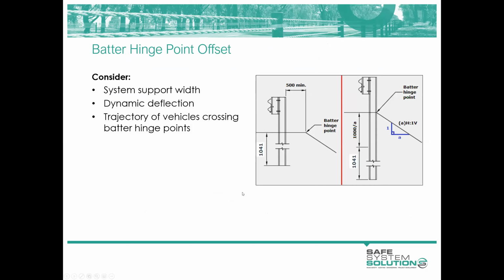So Jamie, there's a point that's come in. Currently, with the 1 metre wide centre line, we are adopting on high rank roads, rank 3 and above in New South Wales, we're in a position to afford more than 3 metre barrier offsets. Yeah, that's interesting. If you can get more than 3, I would strongly support that.